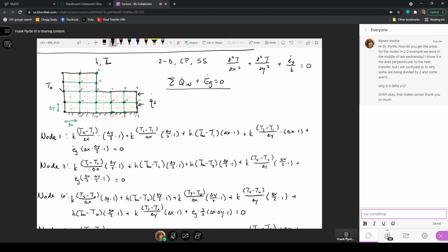There'll be temperature variations as functions of X and Y throughout this entire volume, and node T10 is the average temperature of all those. Now, if I needed greater resolution, I would just decrease the value of delta X and delta Y. That would yield more nodes, but that would also mean that for all of those additional nodes, the area for which that node is representative of the temperature gets smaller, because delta X and delta Y get smaller,